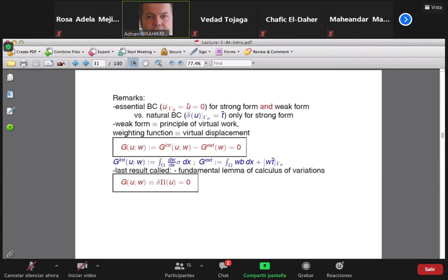In other words, if you want to find out whether a particular configuration of a 1D bar, which is loaded by some kind of loading, is in equilibrium, you imagine you apply a virtual displacement. In the 1D case, it can only go along the x-axis. And so you can then establish the work of the internal forces, which is basically sigma times dw/dx, which is basically the virtual deformation. And you integrate the contribution of all these sigmas along the bar, that means from 0 to L.